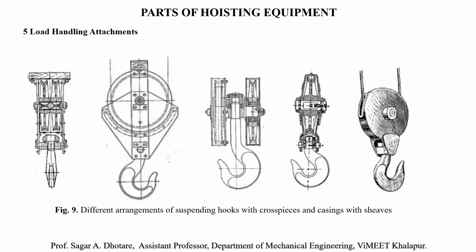Many manufactured goods or packages are provided with hooking facilities, for example a ring, bell, holes, etc. After the forging and machining operation, the hooks are annealed. The inner diameter of the hook should be sufficient to accommodate two strands of chain or wire rope. The load is always carried by the four element slings with two loops.